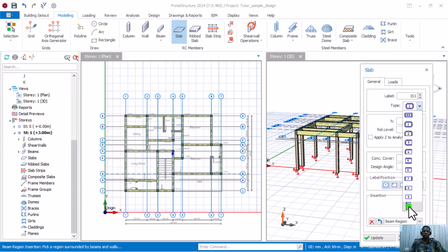When you're doing more of a cantilever that is fixed at one end, we'll use number 2. So depending on the kind of slab you're designing, this is what you use to design. In all of this, we'll be using 1 because we have beams at all sides. Okay, we'll be using that. When we want to design the one that has beams at both sides, then we can come to look at number 4. We want to design for this. Then we can use number 4 to do that design. But for now, we'll just click on number 1, because that is the option that relates to what we are considering for today.